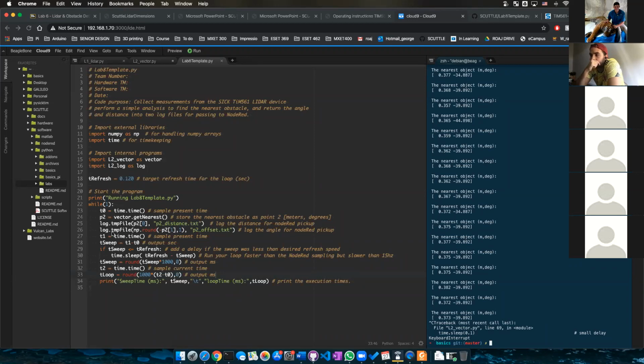what's called an RSSI value. So I pulsed something and how bright was the reflection. That's basically what that is. So if the reflection was very dim, then you'd have a lower RSSI or a lower signal strength. And if it was a higher reflection, it would show a better signal strength.